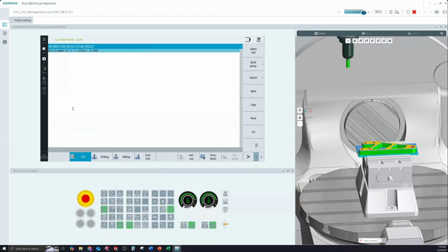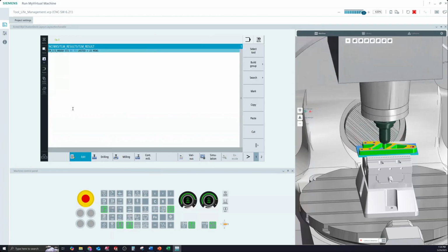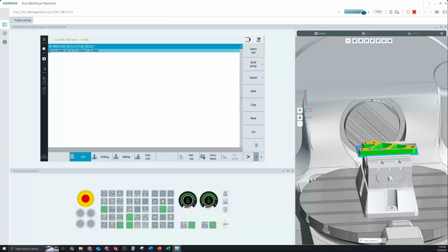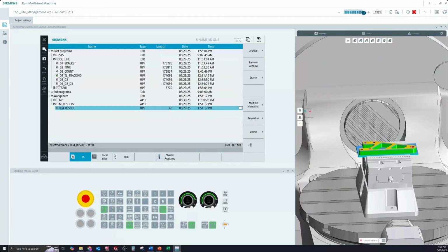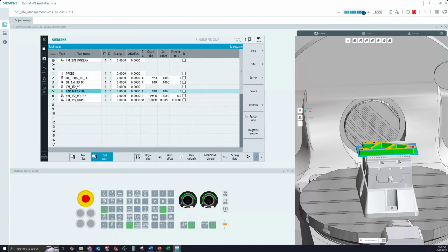So if I open this up, here is our report that we're getting from the macros anytime a tool is changed. We're going to see the tool name, so end mill, half-inch rough, and we'll see some more data for this tool. We'll talk about this in a minute, but sister tool 1, edge 1, D1, and internal tool number 3. That's the internal tool number assigned to this tool. This tool lasted 22 minutes. So what's going to happen is every time your operator changes these tools out and they come in here and they reactivate these tools, it's going to capture that data.